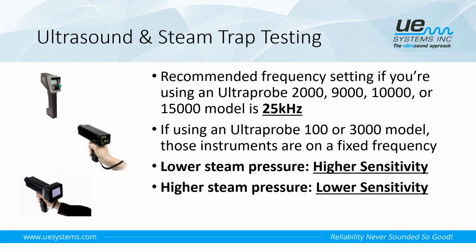So the higher the sensitivity, the more sensitive it is. That's why on our lower steam pressure systems, we want to have the higher sensitivity, because it's just simply not going to be making as much noise as your higher steam pressure systems. So on those systems, you'd want to lower the sensitivity.